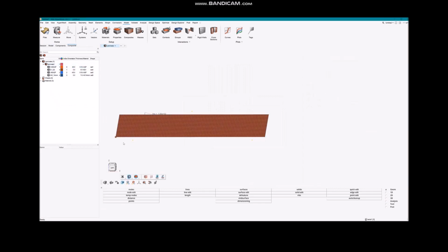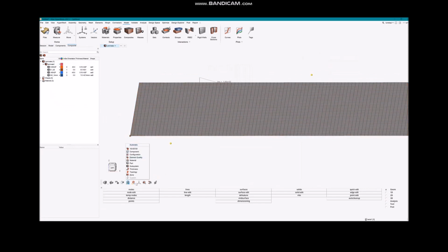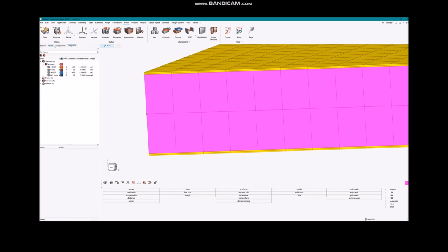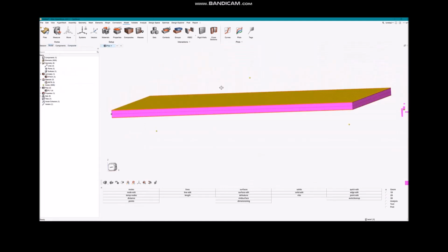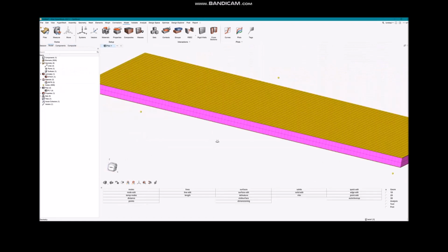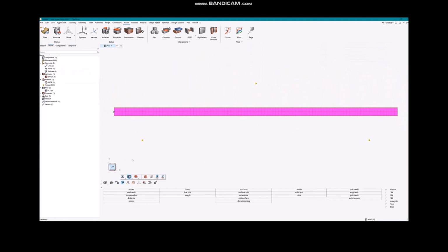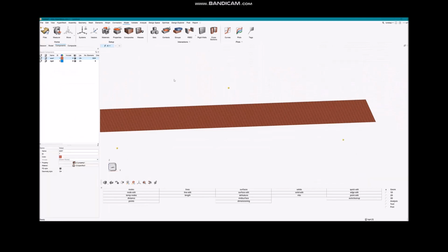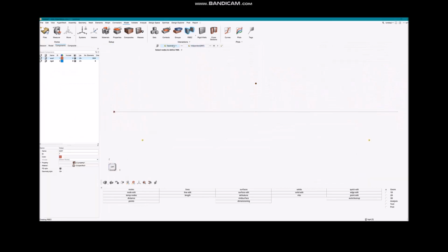Now the laminate you can make under composites, and then drag and drop the plies to the right laminate. Then you also need to add a composites property for this. I use the P card, and here you can check for the right thickness. It's a representation of the panel, and after you check that everything's correct, just add another component, rigid, where we define the test rig itself.